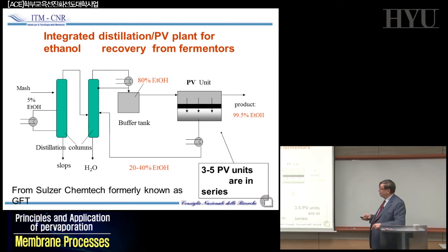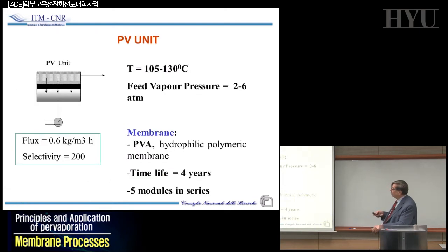We as membrane engineers have the ambition to cancel this system and do everything with pervaporation. However, sometimes it's not convenient. It can be much more convenient to integrate the two and introduce the new operation where there is a limit. This 80% is thermodynamics telling you that you cannot do any better. If you want to arrive at 99.5%, you can operate your pervaporation on the concentrate produced from the traditional distillation towers. And that's something that is happening more and more.